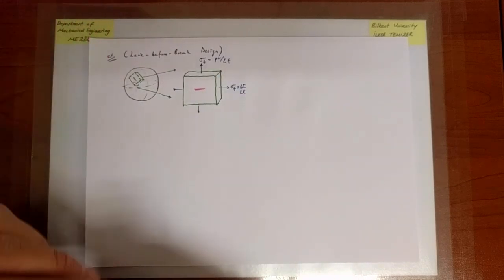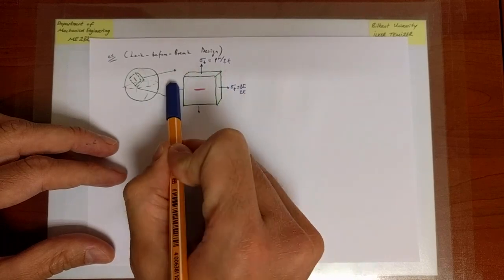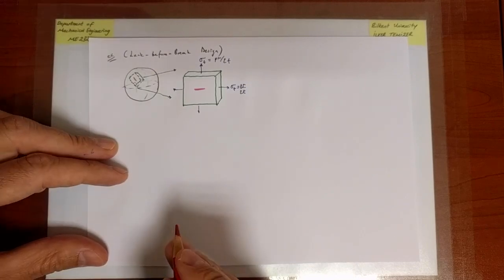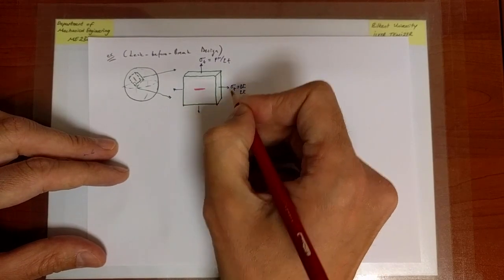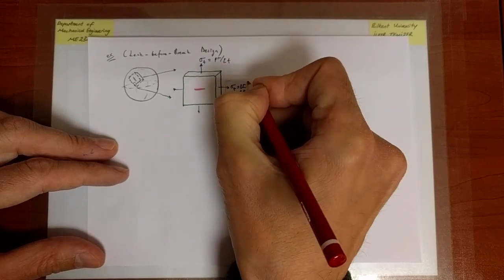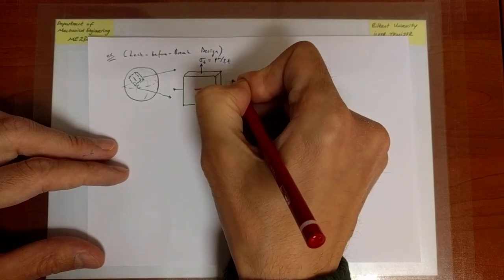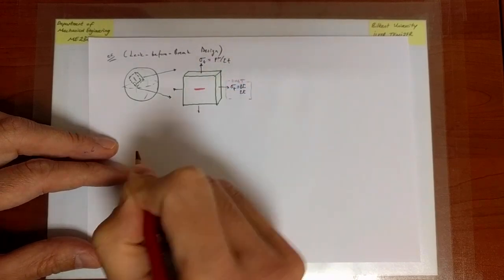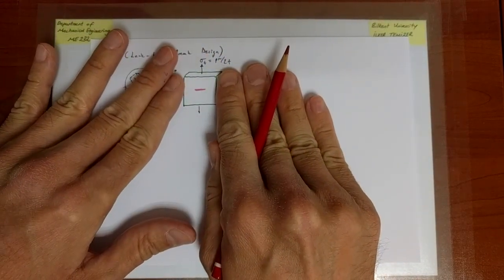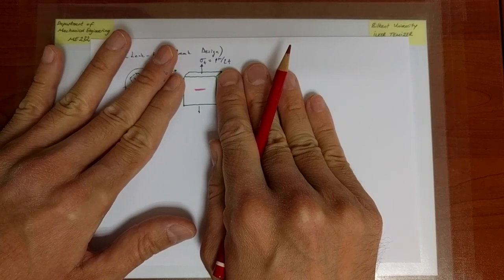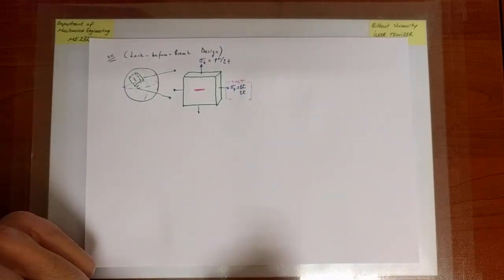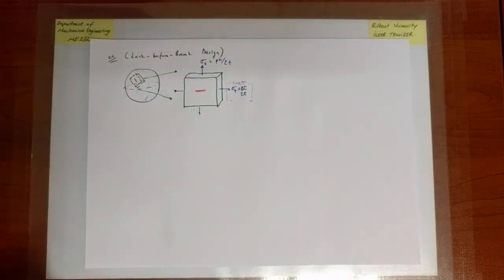And for that reason, it turns out there is no effect of this component of the normal stress. This is what one can at least find from the literature. So the normal stresses in that direction for the purposes of fracture can be omitted. If I want to look at yielding, they're certainly important. But to decide if fracture occurs or not, it turns out I can handle this case as a prototypical scenario. This is not something we can deduce on our own. A fracture mechanics expert has to tell us that this can be done. And that's the way I'm going to address that problem.